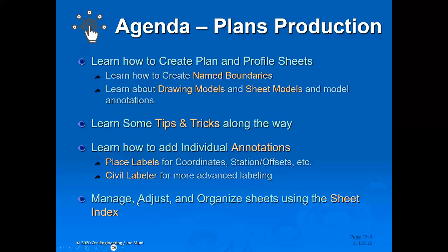And then if we have time, and hopefully we will, I'm trying to talk quickly here, we'll show you something known as the sheet index. I believe that's still going through, I'm going to call it a little bit of growing pains. It's still evolving, but basically it's a way to help you organize all of your different sheets. It's an OpenRoads interface through the Explorer that allows you to manage all of your sheets and quickly and easily push them out to the print organizer.